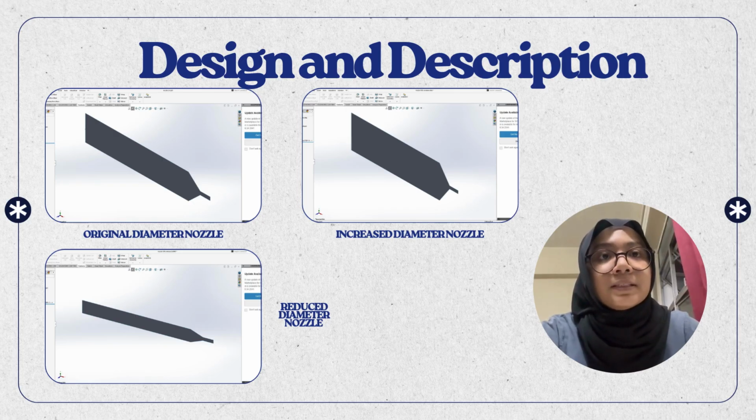As the fluid passes the narrow throat, its velocity increases while the static pressure decreases. If the pressure drops below the saturation pressure of liquid hydrogen, cavitation occurs. The simulation result shows that the 50% larger inlet produces a larger low pressure region, resulting in a larger vapor pocket. In contrast, the 50% smaller inlet limits the increase in velocity and maintains the higher pressure and reduced cavitation.